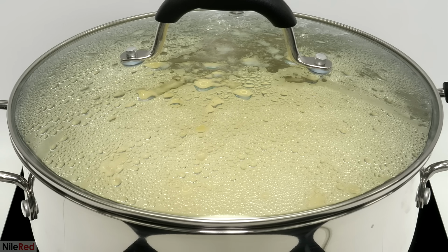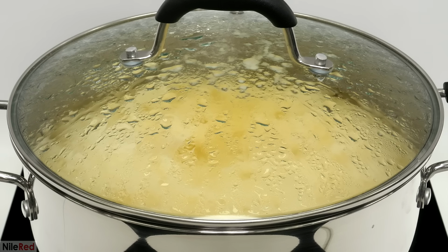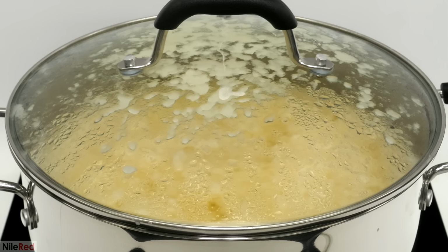Under these conditions, the cellulose fibers were being attacked by the base and getting partially degraded. This caused a lot of the bonds between the fibers to be broken, which allowed them to separate and become less densely packed. It was also chopping up the cellulose fibers into smaller pieces, and their average length was going down a lot.